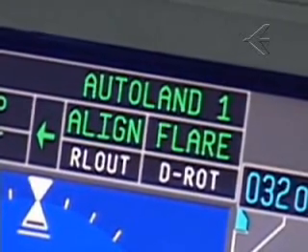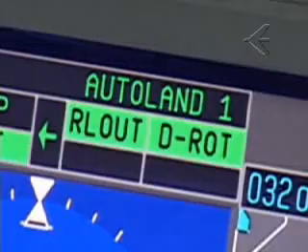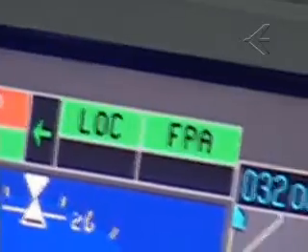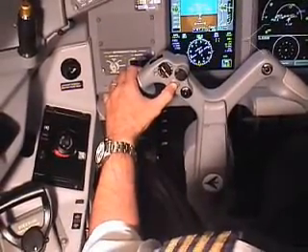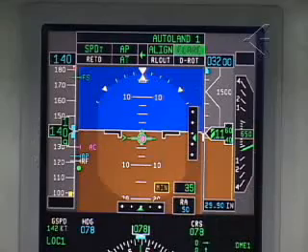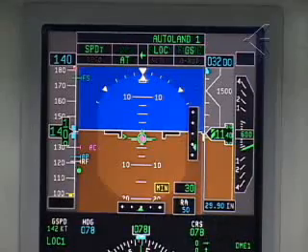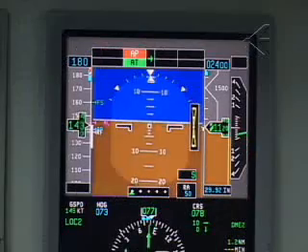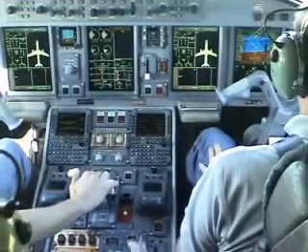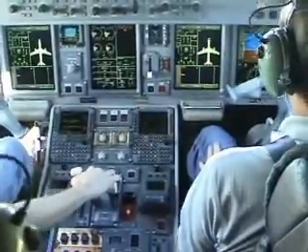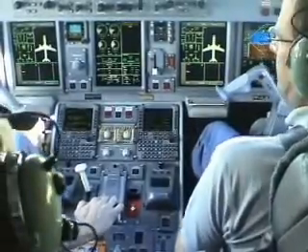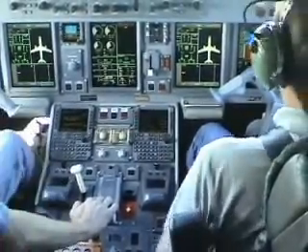On the Autoland 1, the autopilot will disconnect automatically 5 seconds after transitioning to rollout and derotation. However, it is recommended that autopilot be manually disconnected as soon as nose gear touches down. The Autoland 1 status is removed and the flight director modes and cues are removed. The autopilot visual and aural warnings are initiated. The pilot must then take control of the airplane, proceeding to the deceleration with manual or automatic brakes, maintaining runway centerline and applying reverse thrust as required.